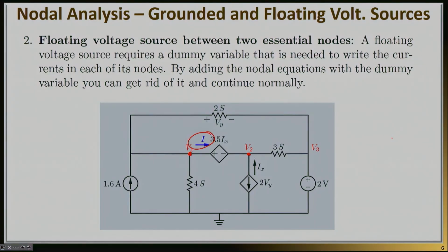Now, there are other methodologies you can equally well use to deal with this. For example, in other textbooks, there is the concept of a supernode, which essentially does the same thing with a fancier name. In other textbooks, you will also find something called modified nodal analysis, a technique specifically made to deal with floating voltage sources, and essentially does exactly what we did right here. But I really don't think you need this type of fancy names. All you need is a clear mind and a logical approach to things, and you can very quickly get the solution as we're discussing here.